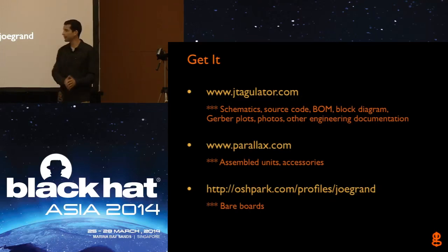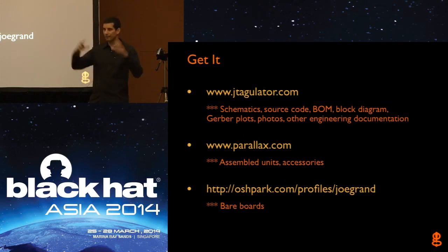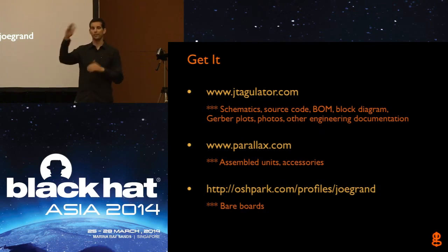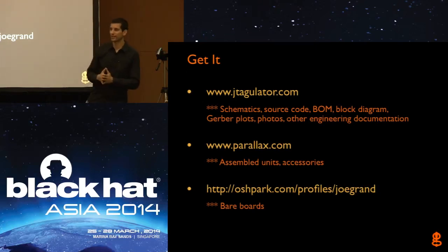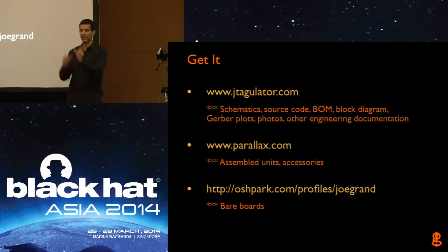OSH Park is a guy out of Portland named Laen, that's his handle, and he fabricates circuit boards for the hobbyist community and basically batches and copies everybody's designs onto a giant circuit board panel and then gets that fabricated because the cost of board fabrication is really determined by the size of the panel. So if you only have a tiny little part, you might still have to use their minimum panel size. So what he does is batch everything together, and so you wait a few days longer, but now you pay some few dollars per square inch to get your boards back. So I uploaded the designs to there as well, so you can always order from him.